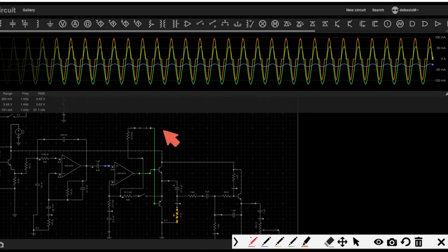I'm talking about this distortion in the orange line. You see here, it's everywhere. The current flowing into the capacitor in your speaker is getting distorted. Some break is there. The reason for that break, that distortion in the current flow, is that 0.7 volt, the excitation voltage required for the transistor.